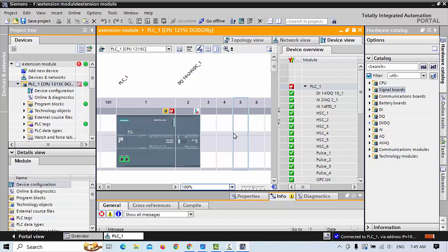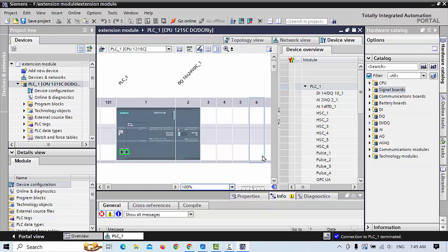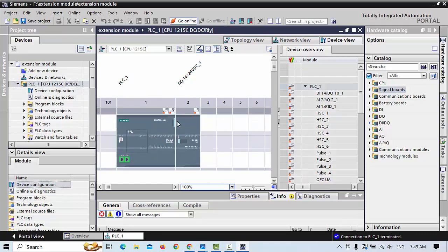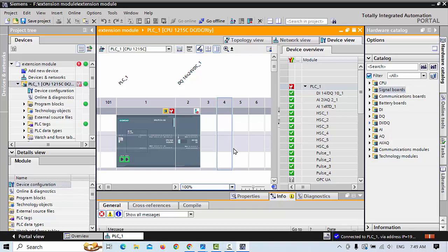when I connect it again, how can we connect it next? We first have to stop, go offline, wait for a second, and then go online. Or you have to stop the power of the PLC, because maybe this issue can also not be solved otherwise.